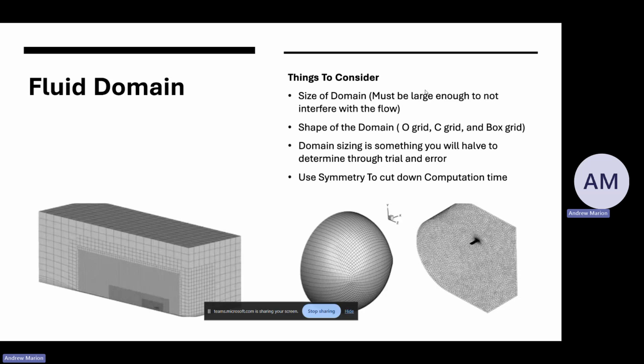So to illustrate this, if this is the front of your fluid domain, and your air is coming in at straight lines, it's going to follow along and it's not really going to interact with the top. So that's fine for this. But typically, how we do angles of attack is you don't actually change the position of the aircraft, because then you've got to remesh and redo everything, a lot of work.